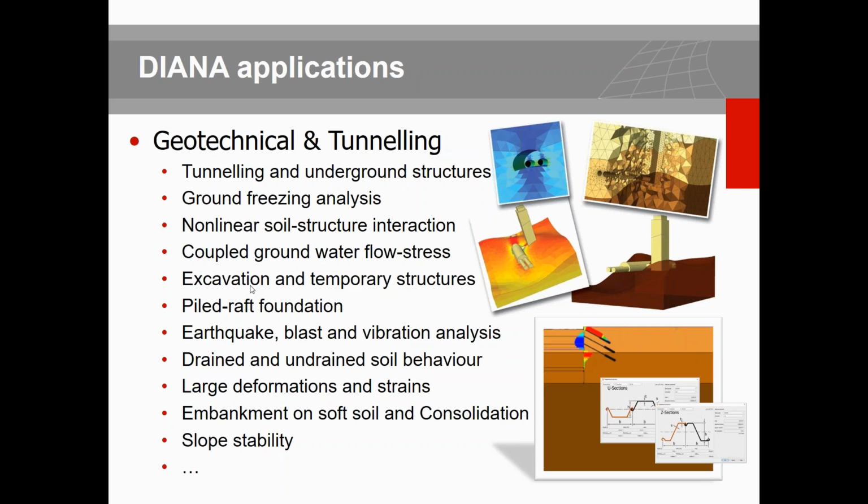You can use Dana in the context of geotechnical tunneling, mining for the earthquake, blast, and vibration analysis. You can consider the drained or undrained behavior of the soil. You can use Dana for embankment and consolidation, check for slope stability in conjunction with earthquake. So you have seismic analysis and you want to see the stability of, say, your model throughout time steps. That's a fully coupled implementation that we have in Dana. You can take benefit of that, and many more that we can go through as we go through the